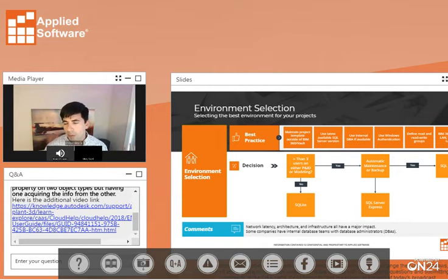A LAN would be when you have your project on a server, so you have a file share server set up somewhere. Again, the main criteria for this is probably our standard engineering firm working environment, where you run your business off a file server and everyone is there in an office. So we would keep this designated for a single office location, and then have multiple people, 5 to 15 to 20 to 40 designers, or sometimes more, all working off one project. With a LAN, you generally are going to use SQL Server, especially once you get more than 3 to 5 users. SQL Server becomes a requirement.